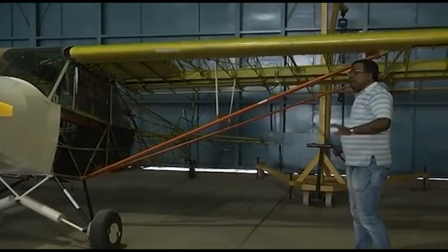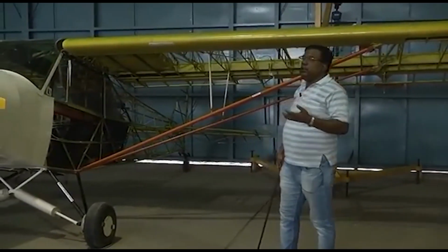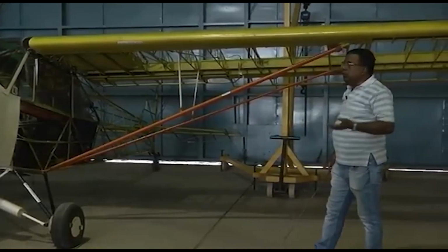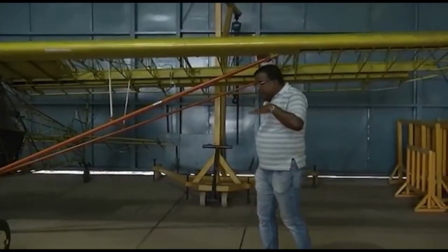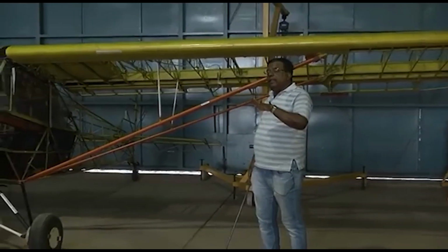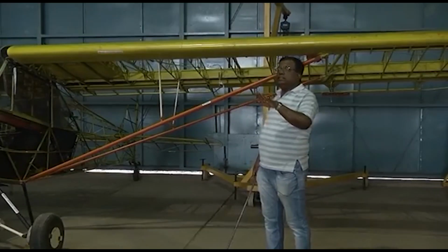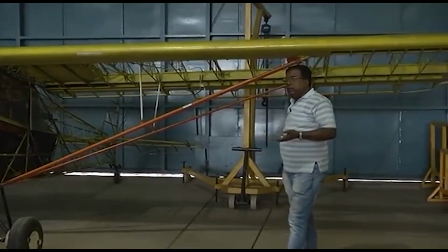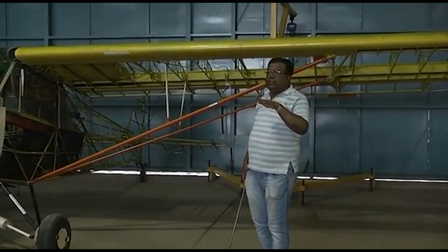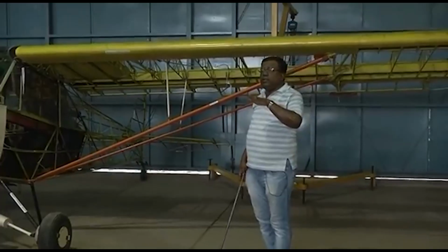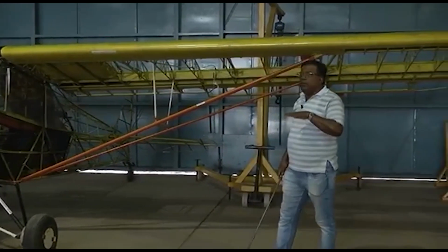But why all these things? Please understand, finally to take off, I want to take off at the lowest possible speed. And that you know by now, that is possible when the CL max is large. That means for a pilot, theoretically speaking, he will try to fly at an angle during takeoff which corresponds to near alpha stall, that is near CL max, which generally may not be really realistic. So what is done? You try to fly at a high angle of attack. In a sense, compared to 2-3 degrees, you try 8-9 degrees and have sufficient speed and you go for a takeoff.